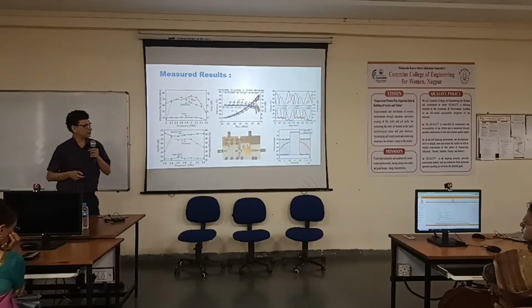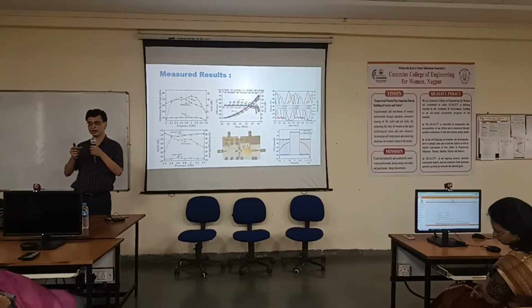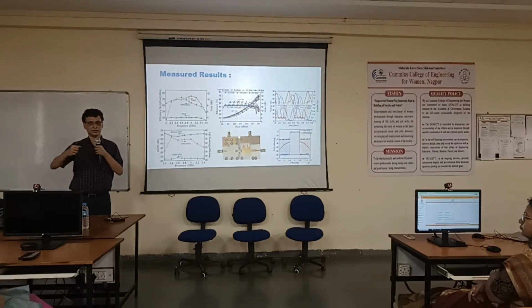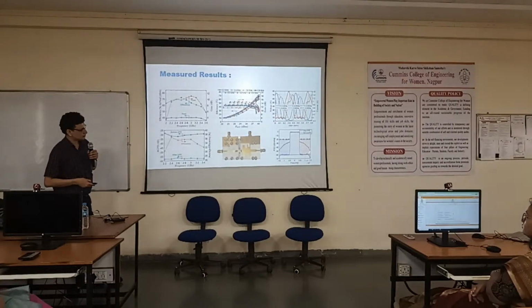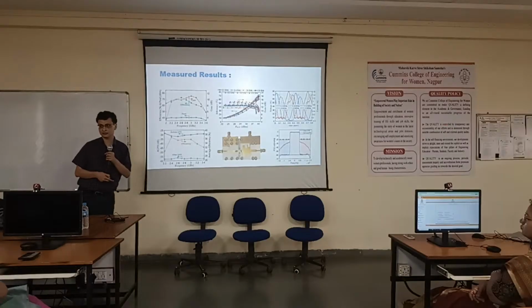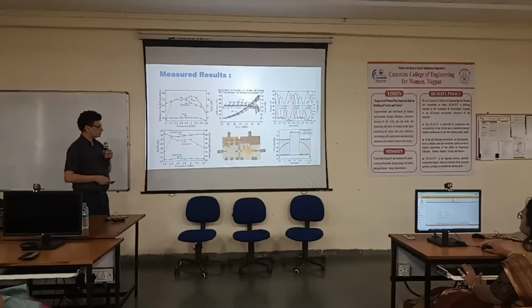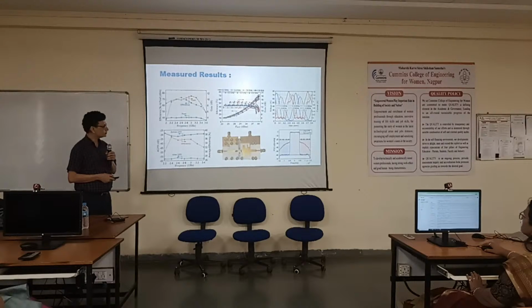Now, one effect of non-linearity is spectral spreading. You might know this, that if we pass a spectrum through a non-linear system, at the output, the spectrum spreads, the frequency spreads. So this is the output, this red line was what was happening before linearization. And after applying the pre-distortion linearization, this is this blue line. So this red line got reduced here. This is an actual 4G LTE signal, okay, that was produced using a digital signal generator. And so this is the proof that this algorithm works.